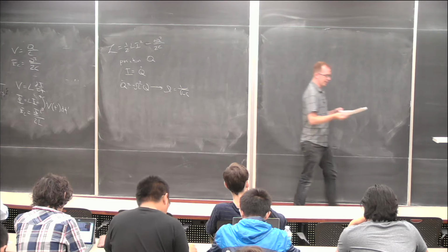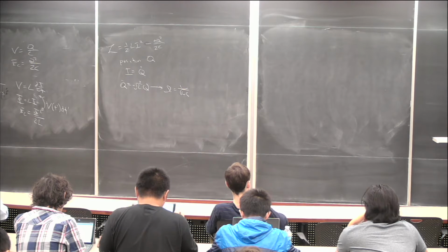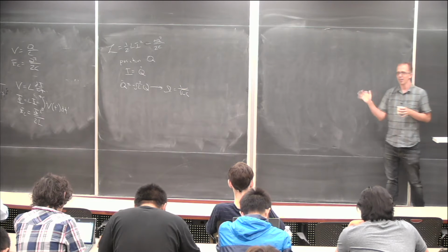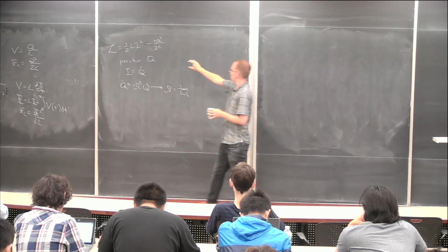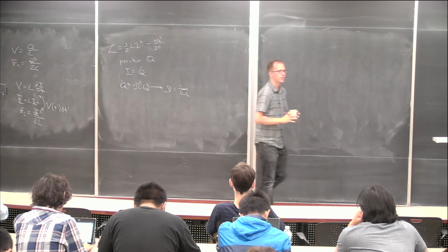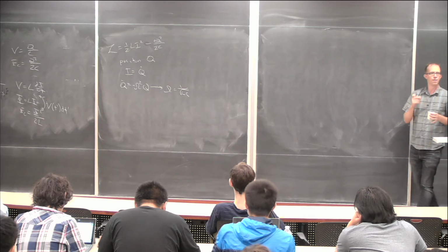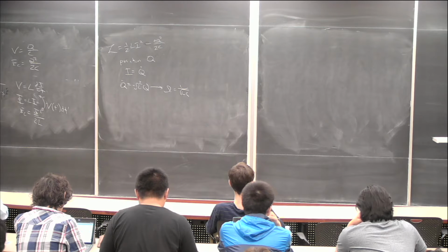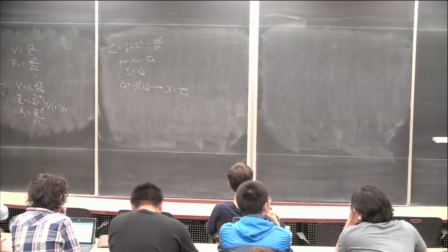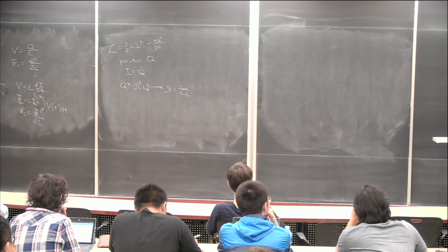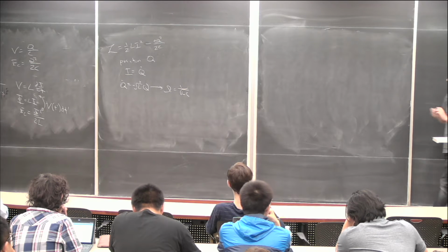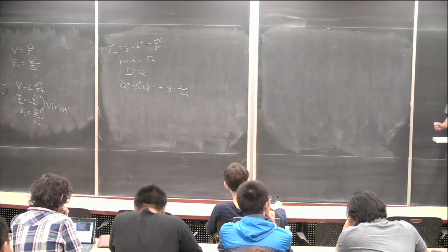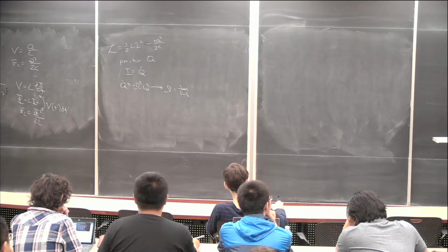This gets a little bit confusing because everything works out fine, but this is not the way that we like to do it in the superconducting circuit world, even though I think it makes the most intuitive sense to call charge the position and current the obvious derivative of charge with respect to time. We like to deal with fluxes as our position variable in the world of quantum computing, because it makes dealing with Josephson junctions easier.